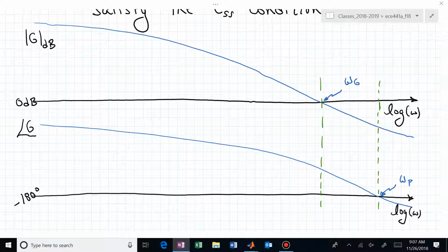If I want to change the gain in this system on G, if I increase that, let's say it was nominally 2, and I say, let's make it 5, do I now have to resketch the phase? How does that gain influence the angle or the phase information? Does it? No. So the gain, I'm simply going to shift up or down with a gain increase.